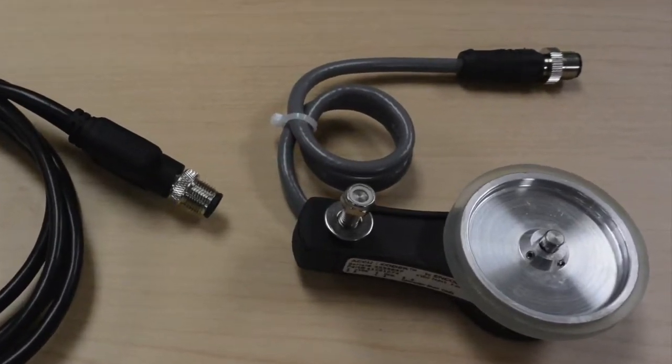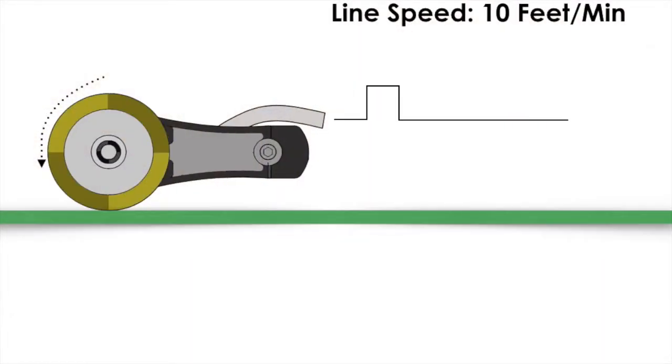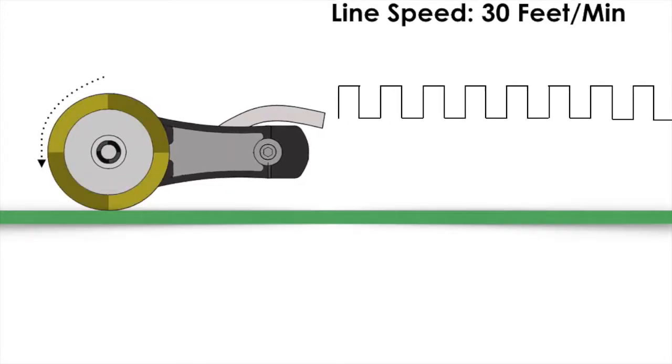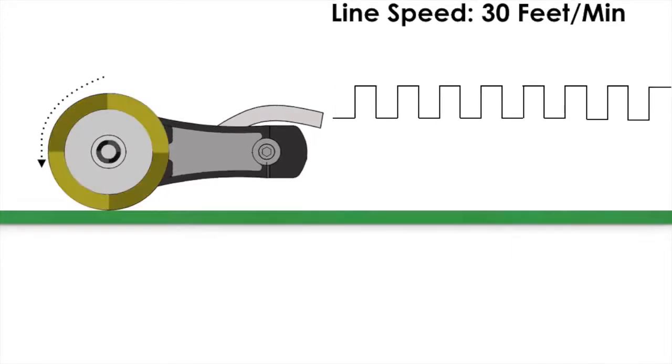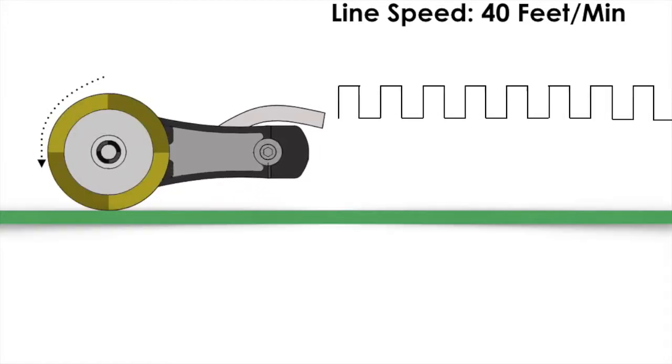line speed encoder. A line speed encoder measures the moving conveyor belt speed by providing position pulses into the TC12 inkjet coder. The change in conveyor speed results in a change in the rate of position pulses the TC12 receives.